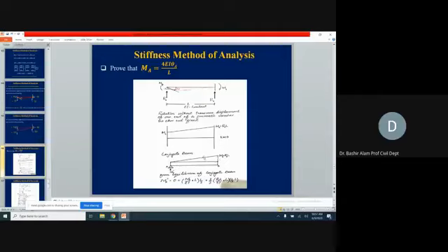We are left with this triangle now, since we already used MA. The remaining vertical ordinate is RA times L. The equivalent resultant of this triangle is half of RA times L times this distance, which is L, so half times RA L over EI times L. And the moment arm from the load intensity is 2/3 of L, written here as 2/3 L.